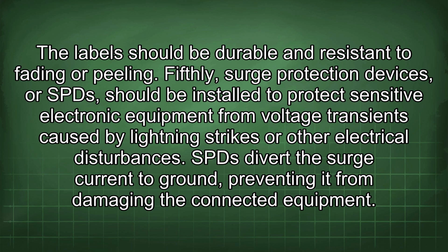Fifthly, surge protection devices, or SPDs, should be installed to protect sensitive electronic equipment from voltage transients caused by lightning strikes or other electrical disturbances. SPDs divert the surge current to ground, preventing it from damaging the connected equipment.